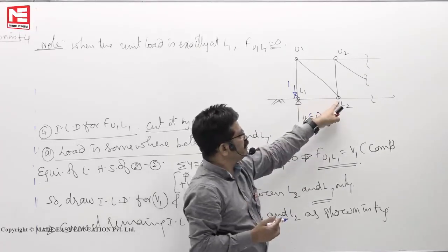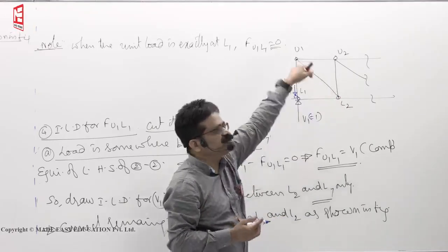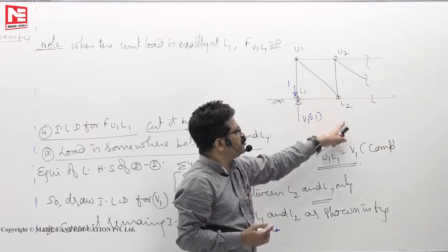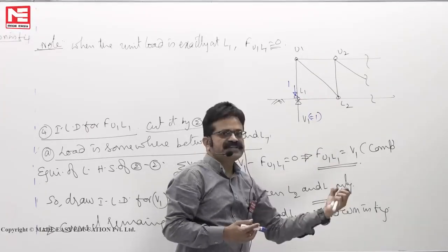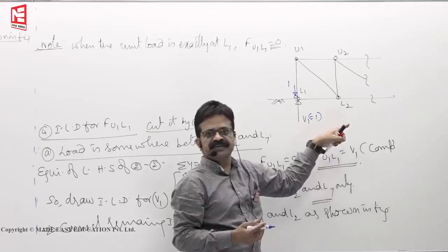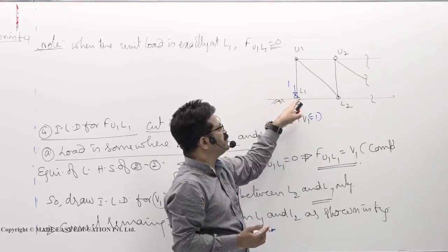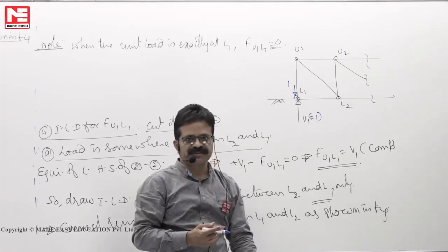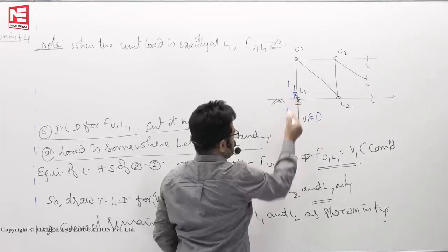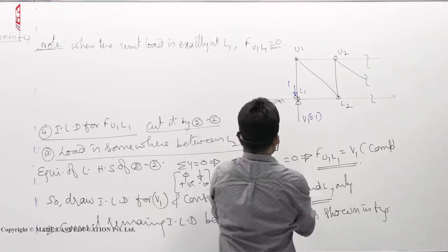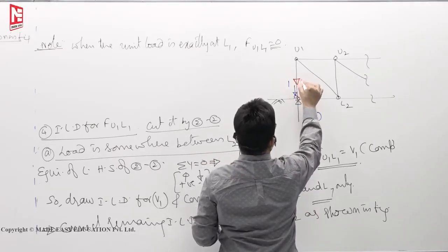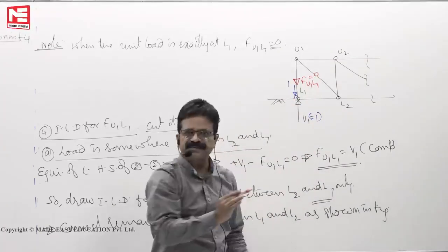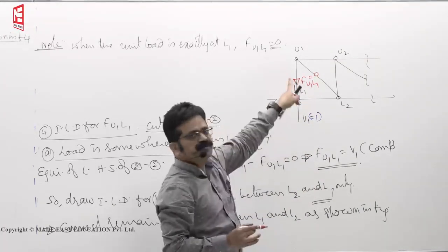If it is in air like this, then the cross girder first transfers load to the joint, and there is no support there, so whatever load is hanging is taken by the members only. But here, when load enters the bridge, it is not taken by the members. Load is directly taken by the support. So these two balance themselves. In such cases, U1L1 has to be 0 because they are already in equilibrium by themselves. Downward one, upward one, they balance.